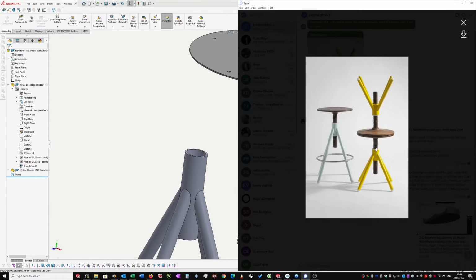I've switched that off. If I just click on this little arrow, I can switch on the temporary axes view button, and all of the axes are now visible. I'm going to select this one and the one on the actual base, and then make them coincident. Alright, so this can now move up and down, but it can't move away from this axis. Okay, so let's move that out of the way for now, and then insert the other component.